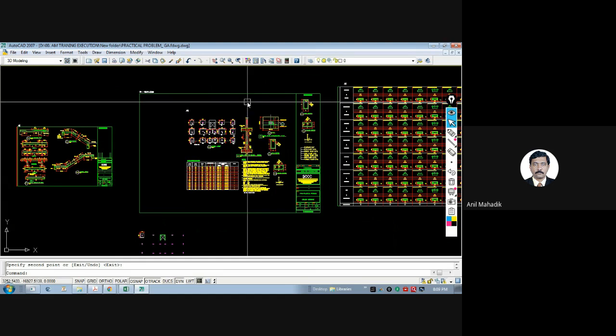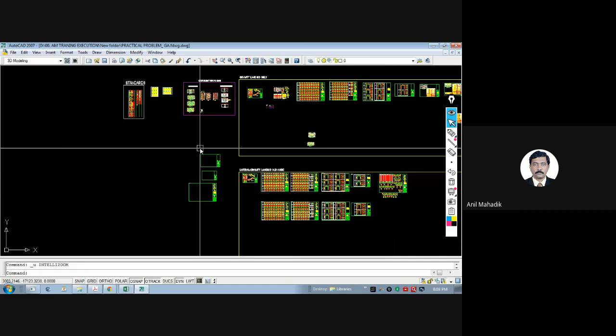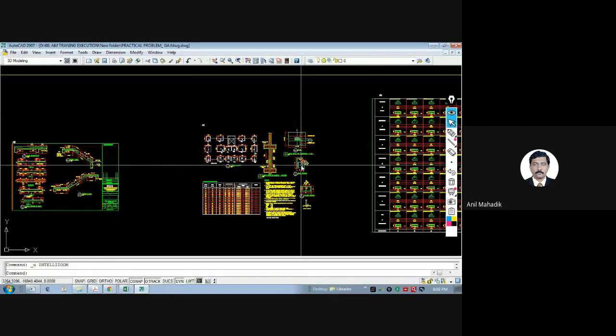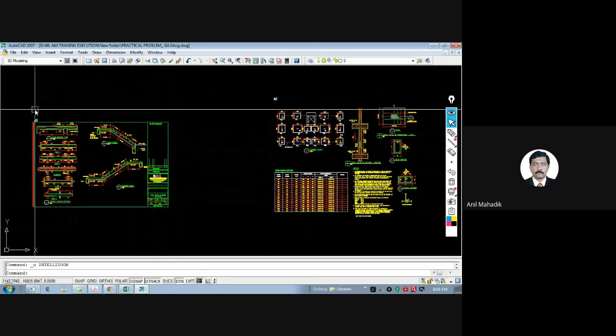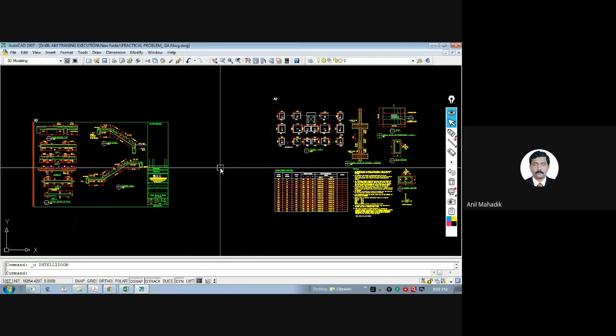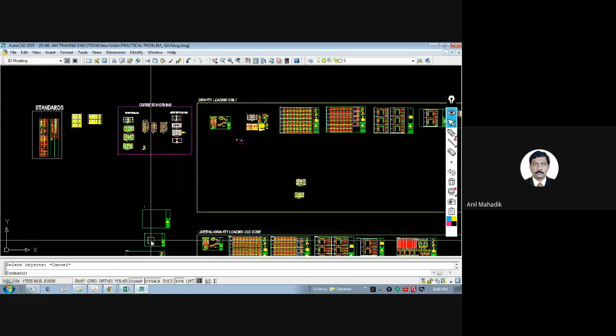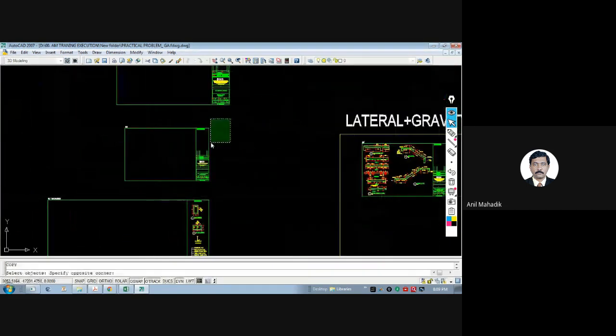So this way we choose the sizes of the paper. You can either prepare the drawings and then decide the paper size, or you can think of paper size in the beginning also, but it's up to you. Better way, do this first and then put the papers. And you can have a choice that if you are not comfortable with A2 size paper, then you can have A3 size paper, but you can split your drawing in two parts. For example, let's say this is your A3 size, which is smaller size.